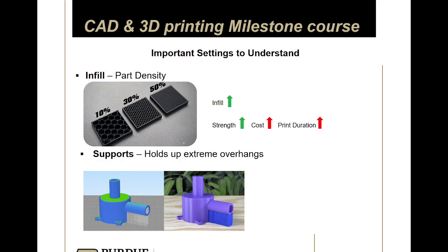So I'm going to pass around this support that I have. I was printing a helmet for someone, and a helmet's basically a big dome, so the top of it is a really large overhang. It resulted in a giant support. Obviously, this geometry for a helmet is kind of necessary, so I needed the supports, but if you were designing something else, then you can remove the need for that. But yeah.